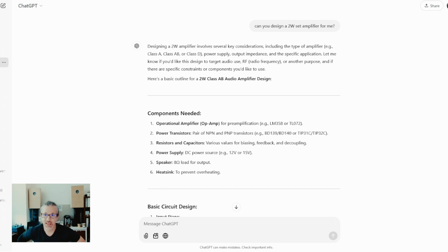The AI missed one thing here, that I already specified SET, which means single-ended triode, and AI didn't understand the concept of SET. So that's why it put Class D in it, because yes, there are single-ended designs in the transistor or solid-state domain, but the T means triode and it means vacuum tube. So we are Class A or Class AB, or maybe Class C in telegraphy operation, but certainly Class D is not the answer for this.